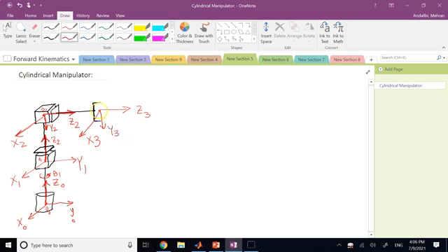Good. So this is going to be my origin 3. Y is clearly the direction of the slip, which is the opening and closing of the gripper. Z3 is the approach direction, and X3 is the normal. So here you see I'm completely observing that NSA rule that I mentioned, but I did not necessarily have to do that. The only thing is X3 could not be the same as Z3.